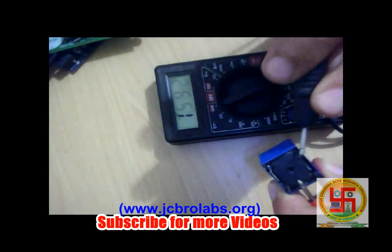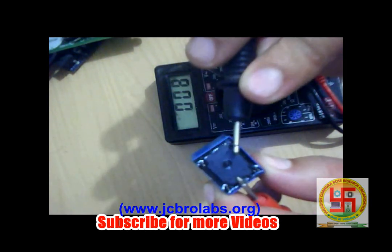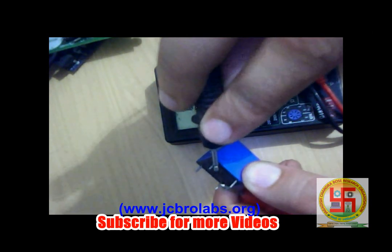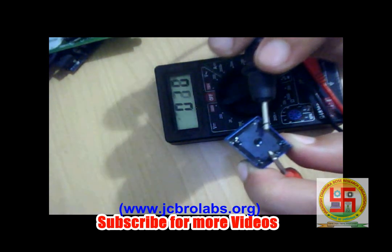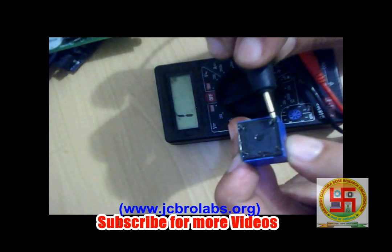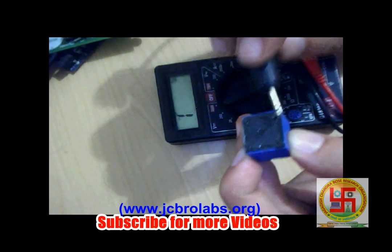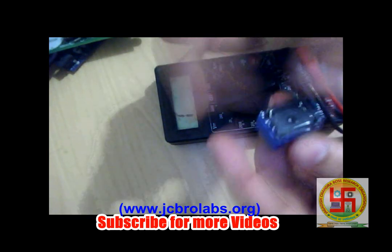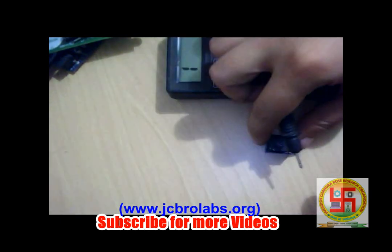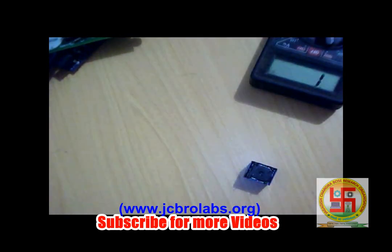Okay, so right now this middle pin is connected to one of the corner pins of this relay. That means this is the connection. This particular pin and this middle pin are connected when no power supply is connected to the relay. That means when no power supply is there, these 2 pins are connected to each other. Now let's check by providing a power supply.